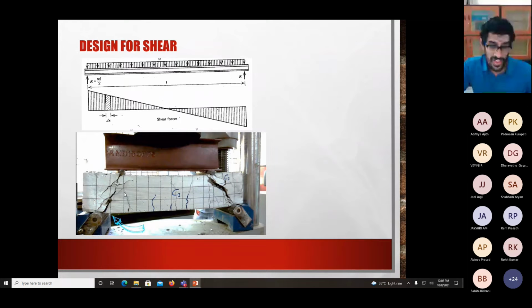Okay. So what is the difference between this and the way the cracks will come if the failure is from flexure? How will the cracks appear if the failure is mainly from flexure? Where will the cracks be? It will be at the bottom, approximately perpendicular. Okay, at which location along the beam?